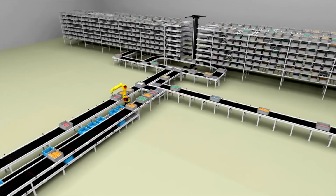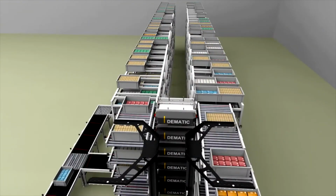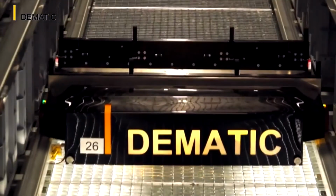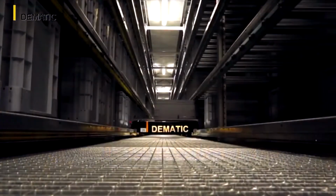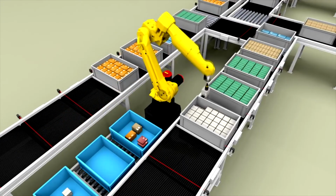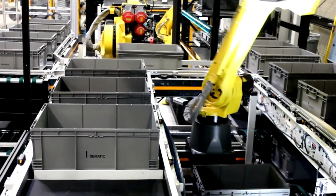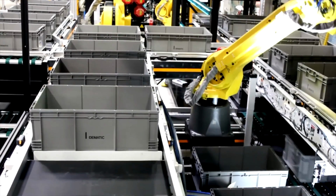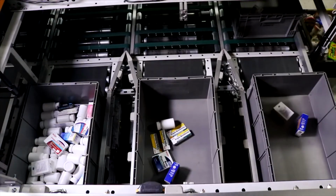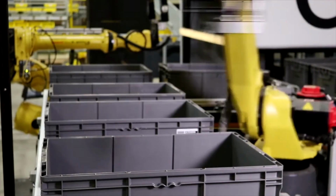Here's how it works. Inventory is received and staged in a high-density automated storage subsystem. Typically, there is one SKU per tote. Multiple SKUs are accommodated in totes with compartment dividers. The Dematic warehouse execution software releases inventory totes in a strategic sequence. The tote arrives at the robotic pick position at the precise time it's needed to assemble the order. The number of robotic picking cells is determined by the required capacity. Robotic pick cells can be scheduled to operate 3 shifts a day during peak seasons.